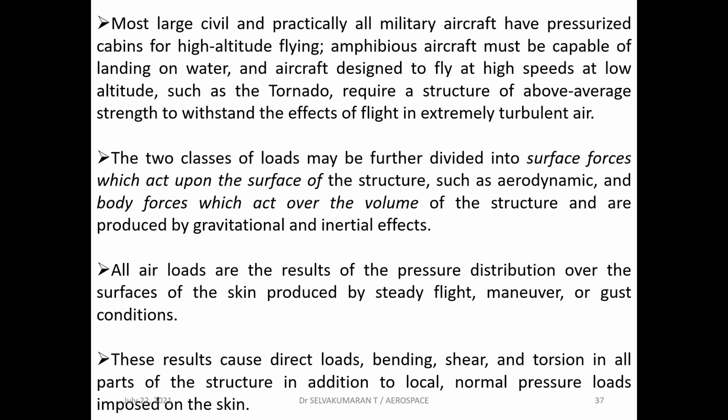All air loads are the results of the pressure distribution over the surfaces of the skin produced by steady flight, maneuver, or gust conditions. These cause direct loads, bending, shear, and torsion in all the parts of the structure, in addition to local normal pressure loads imposed on the skin.